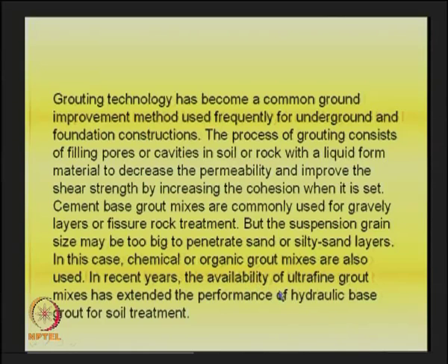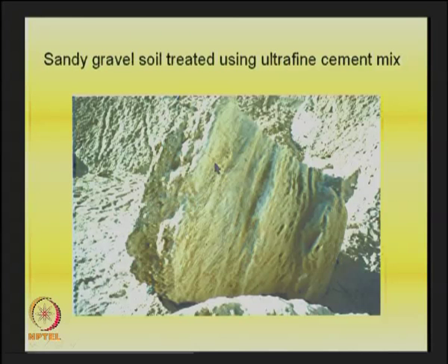Nowadays we even have ultrafine grout mixes, which are very useful for increasing the performance of hydraulic based grout for soil treatment, in the sense that they are going to be very useful in reducing permeability and increasing strength. I would like to show you a typical photo in which sandy gravel is there initially, but then if you mix ultrafine cement grout and remove the soil mass, it is like this. It is so strong.